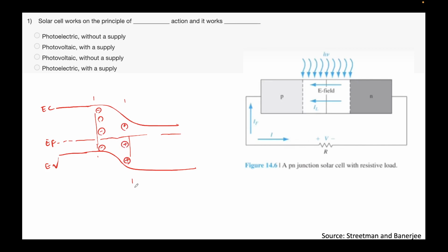Okay, and consequently, as we had talked about, at the metallurgical junction, there will be an electric field only in the depletion region. I'm just drawing this symmetric, but this is just for illustrative purposes, electric field with respect to x. Although in the depletion region we say that it's devoid of any mobile charge carrier, so all the electrons and holes have moved away, and thus we are left with this sort of a static system, so to speak, of just the fixed ions, right? And it's not connected to any external battery, any external voltage source.